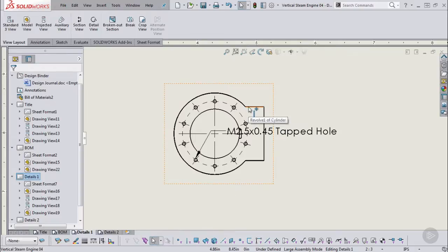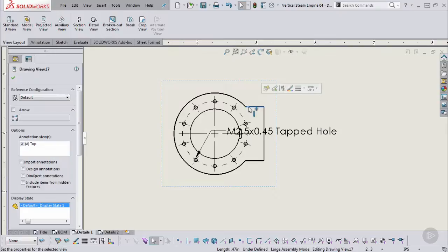All I need to do is select the edge, and in the shortcut pop-up menu that comes up, there's a Hide Show Edges icon, and simply click that icon. Now this has a couple of edges right over top of each other, so that's why we're not seeing it hidden. But if I continue to do that, finally we get a hidden edge.